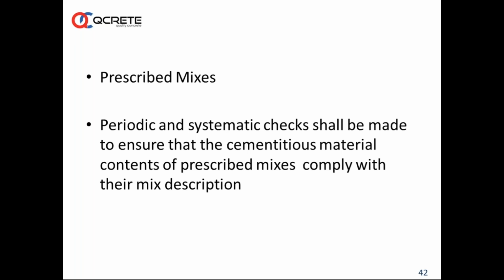And earlier, it was set in other countries, especially in the European codes, long back, that the responsibility of the producer ceases once he just mixes and gives what is prescribed completely. If the customer prescribes everything and gives it to a ready mix company, saying mix like this and give, these are the ingredients, this is the mix design, then the responsibility of the producer just closes if he just mixes and gives. He is in fact not responsible for both fresh and hardened properties. He will only have to ensure that he has mixed and given as per the specification, that all the ingredients have been mixed and given.